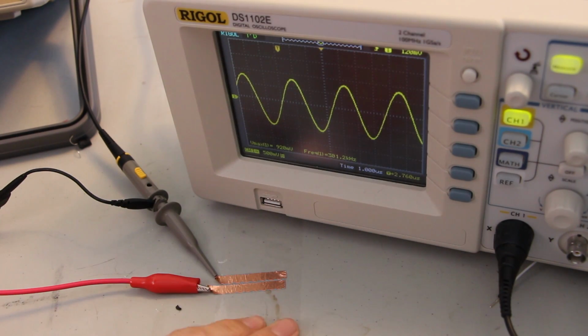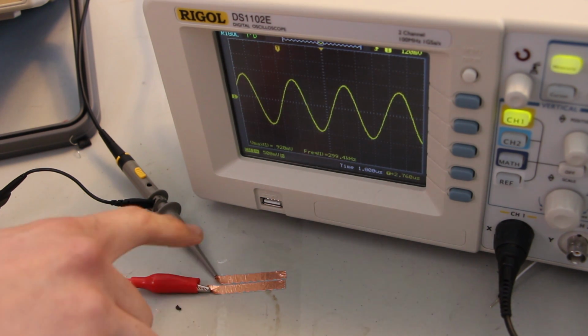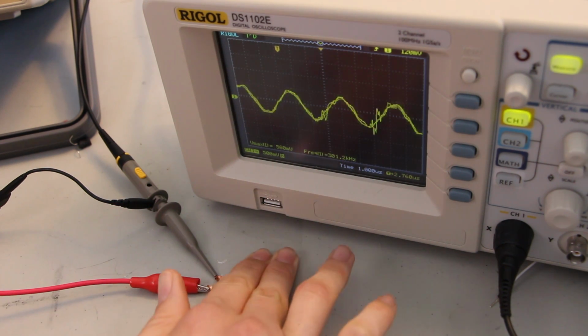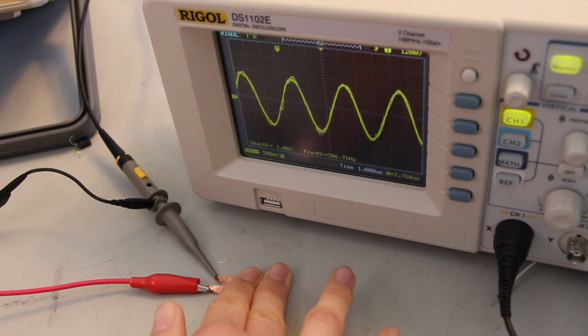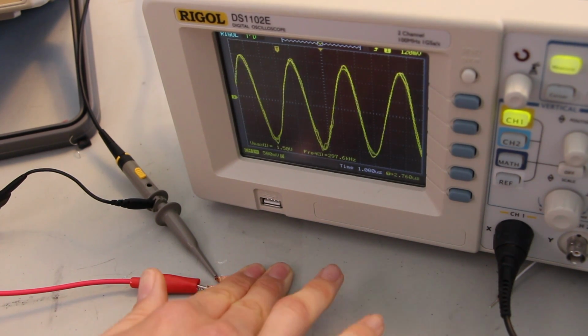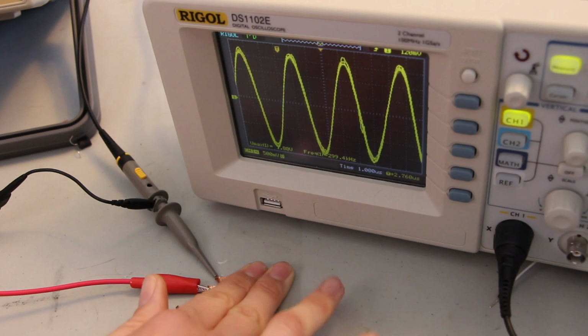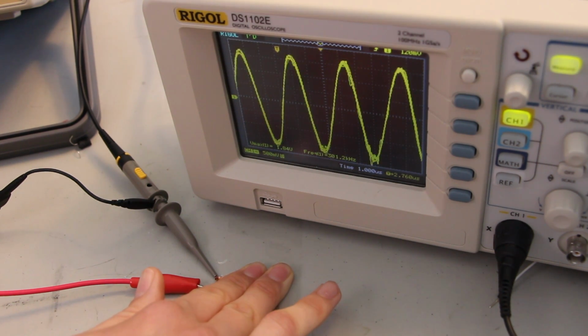This is a very simple model of a touchscreen. It has two electrodes made of copper foil. One's being used as a transmitter, one's being used as a receiver. There's a layer of packing tape over the top simulating the glass. This prevents a direct connection between my skin and the electrodes. But when I press down on both electrodes, there's a strong capacitive coupling that actually increases the amplitude of the signal passed from the generator to the oscilloscope.